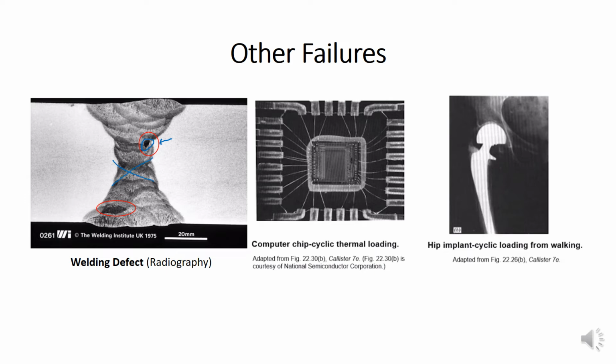and it can lead to the failure of this welding joint. Here you can see an integrated chip. When current passes through these wires, there is heat generation. When the current changes its amplitude, there is a change in heat generation, and it will lead to thermal loading. Due to that thermal loading, fatigue occurs, and sometimes these wires get broken. Nowadays the heart of many electronic devices is this integrated circuit chip, so we need to take into consideration whether there is any discontinuity in the IC chip or not.